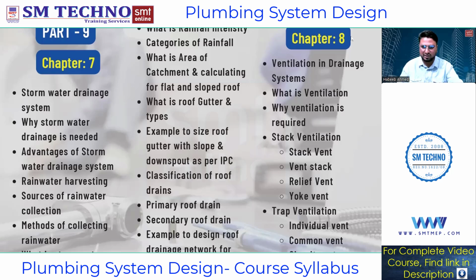Under ventilation, you have mostly two kinds of ventilation provided in a drainage system. One is stack ventilation, or a riser, if you're not understanding stack as of now. A stack is nothing but a vertical main pipe. So here the ventilation is being done with respect to the stack, and we know the stack vent and the vent stack.